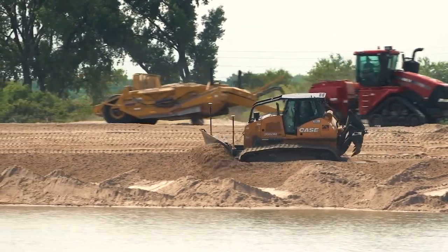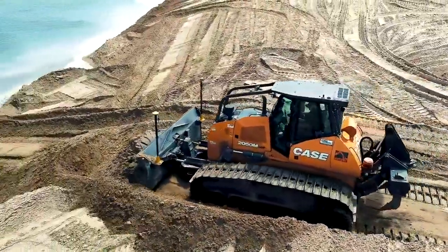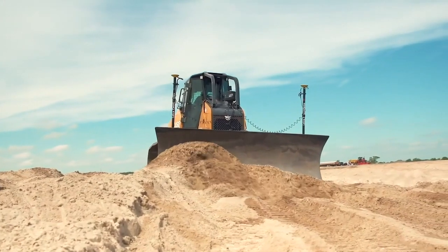Primarily, think of it as another feature or another attachment on the machine to enable you to do more work, or do more work effectively. Machine control, often considered 2D or 3D blade control or excavate systems on excavators, really comes down to making a good operator better, to where they can get more efficiency out of the machine, run fewer passes, put fewer hours on the machine, and basically avoid over excavation or under digging that later needs to be revisited and fixed for one reason or another.